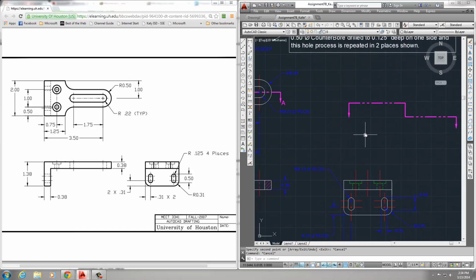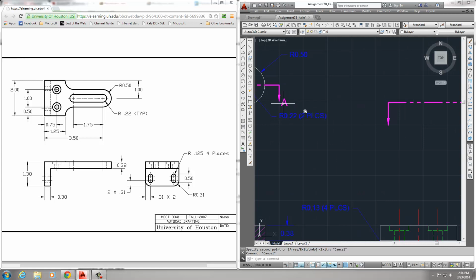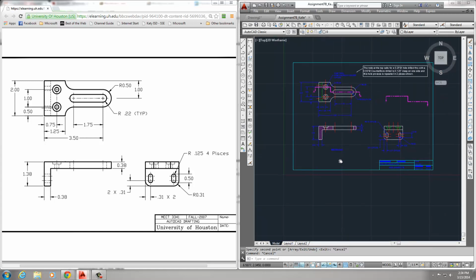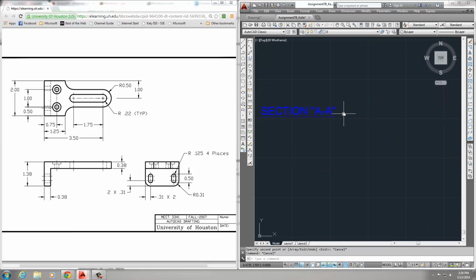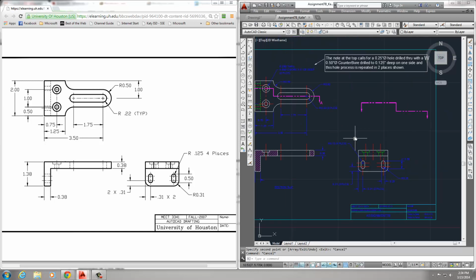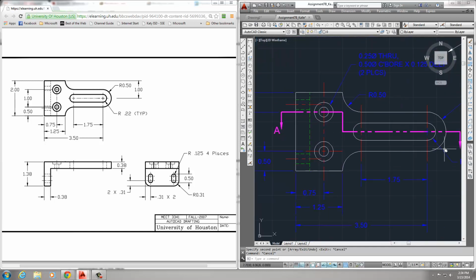And then you just do an M text or D text, whatever you want, to do the A, and drop them in here on both ends. And because you have to title each section line as section, this one happens to be one section, section AA, then the next one would be section B, section BB, section CC, and so forth and so on. In this case, there's only one. Okay, you have to make sure that you see how this thing is cutting.